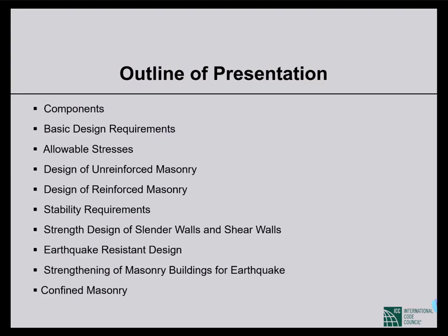That implies that pure unreinforced masonry is not allowed for seismic zones 2, 3, and 4. All of us have to understand that URM, unreinforced masonry, is no more allowed in BNBC 2020 for seismic zones 2, 3, and 4.